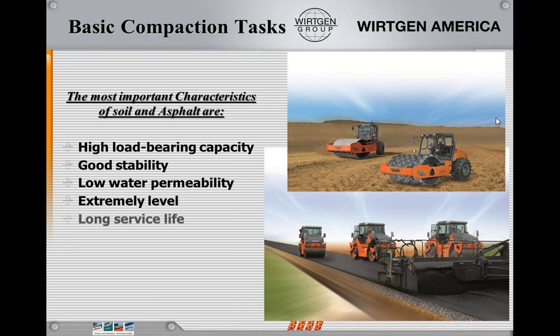Well, by doing so, we also give the material a longer service life, and we have a high skid resistance. I throw the high skid resistance in because it goes back to being extremely level and smoother. The more contact we can have with our tires on the surface of the road, the better the skid resistance we have. You've noticed when you go around a curve or on a road that's bumpy, your vehicle starts sliding sideways or hopping sideways. That less contact means we're not going to have good skid resistance.